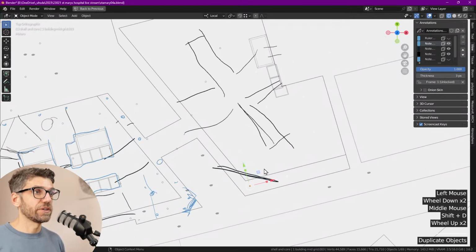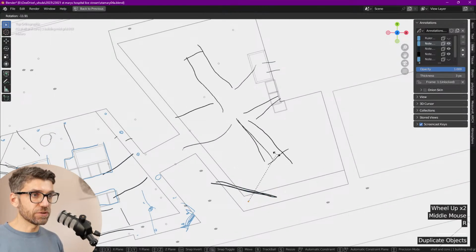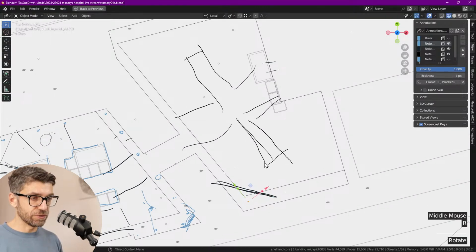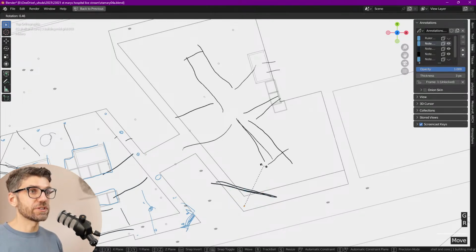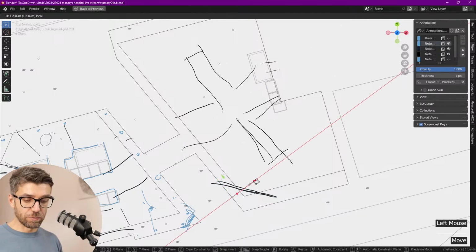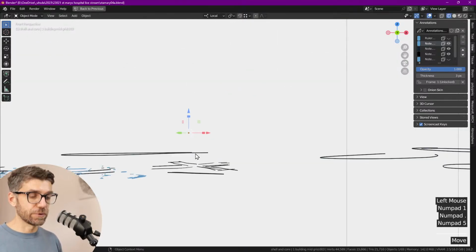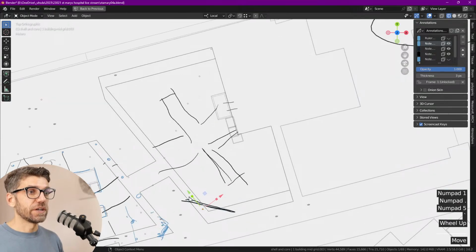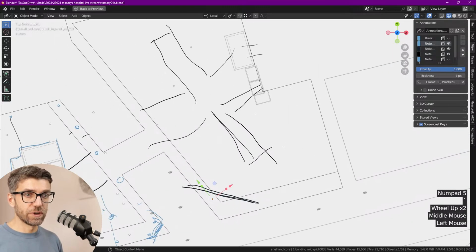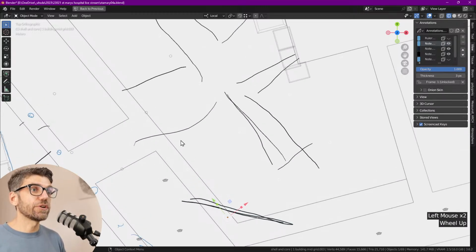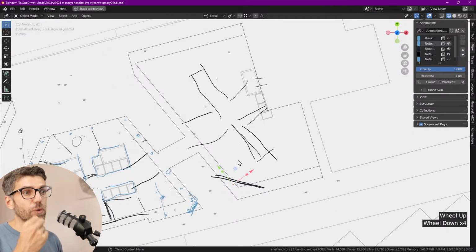Let's think about these cores now here. Now that is going to get aligned. This is the best edge for the majority of the core to be aligned to, just because it's the biggest span. And we're going to do the same thing that we did before. So we're going to align to that external edge, and we're going to move it 1.5 meters back. And that's going to help us with some of our, did that move? 1.5, nope, 1.5 meters. It's going to help us with some of our setbacks on top.